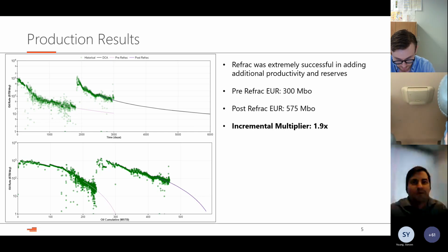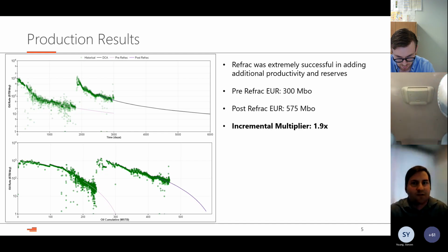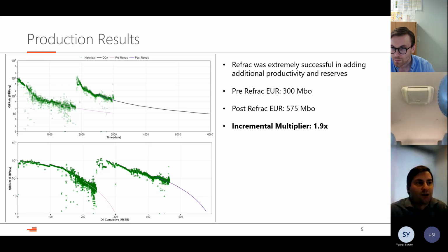I'll say the Eagleford in general is relatively, purposely cautious on what our drawdown strategy is. We can get to very, very high IPs, but we also have very steep declines. So frankly, the NPV of getting aggressive isn't that great. We do typically see in a lot of these refracts, especially the more successful ones, us getting back up to virgin pressure when we turn these wells online. So certainly another indicator that we're accessing reserves that we were never accessing before, due to such wide cluster spacing that is just never draining between those fractures. So we do get close to virgin pressure.